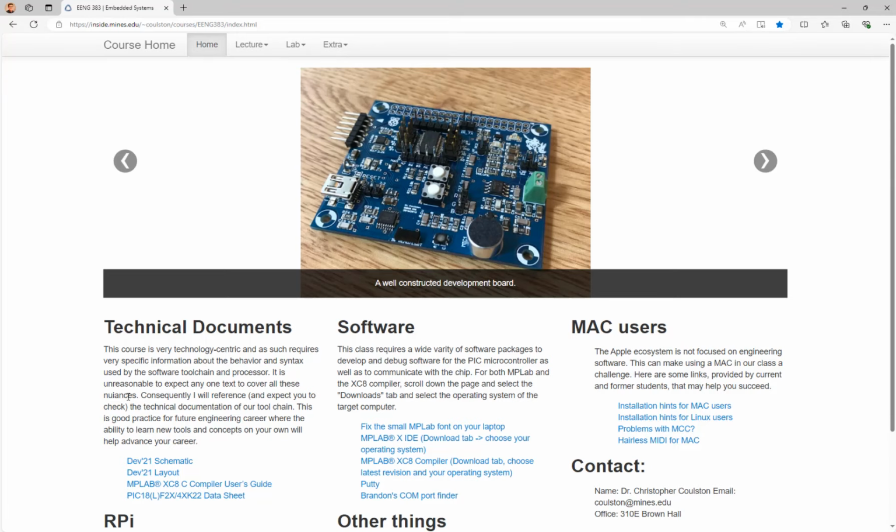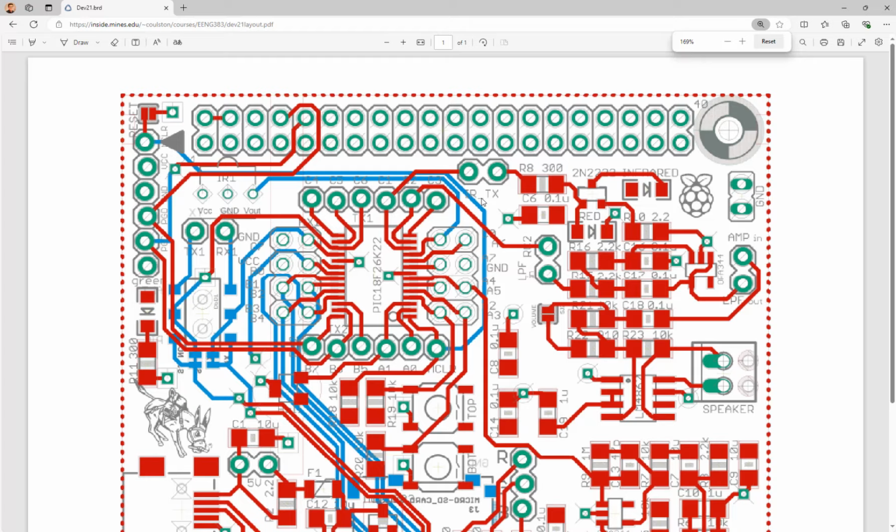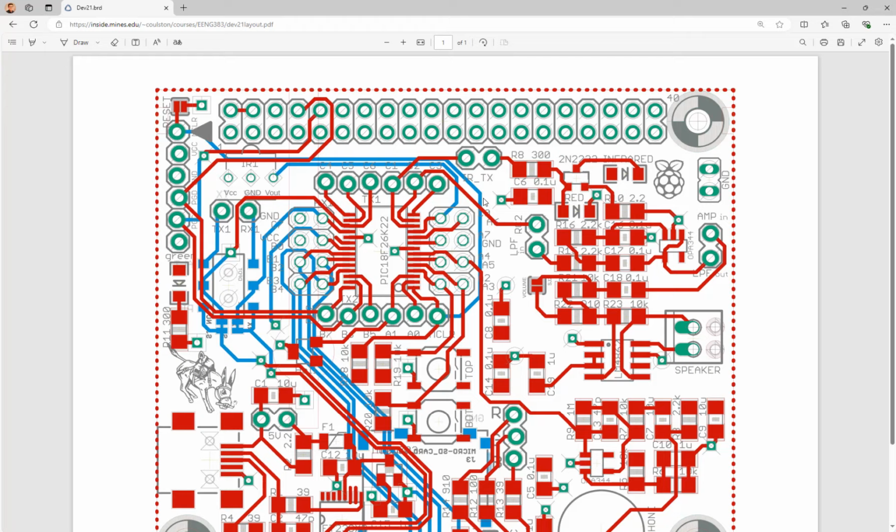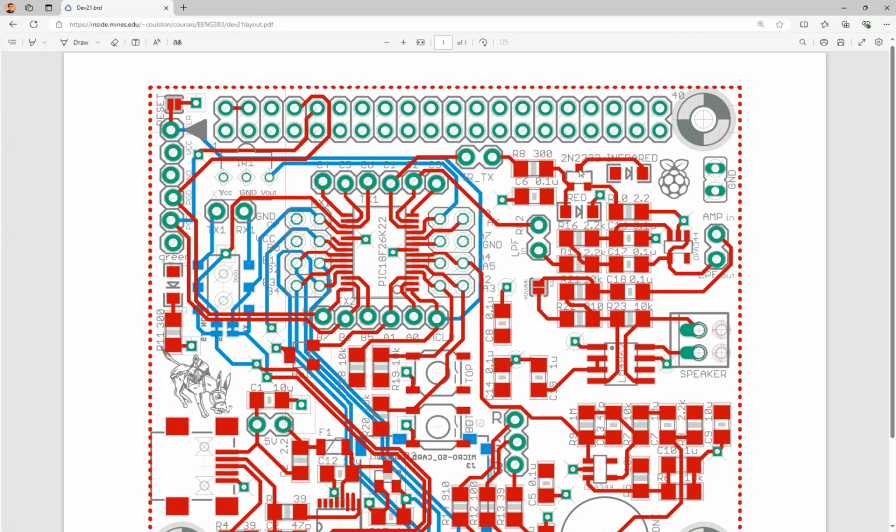You can see it here on the board, on the board schematic layout. It's connected to this BJT as a switch on the top of the board. It's hard to tell, so if you have the board, you can grab it and take a look. It's a little tiny LED on the top, and the receiver is on the left-hand side of the board. It's called a decoder or receiver. It receives the pulses, decodes them, and converts them to pure digital signals. The LED is emitting over here, and the receiver is here.